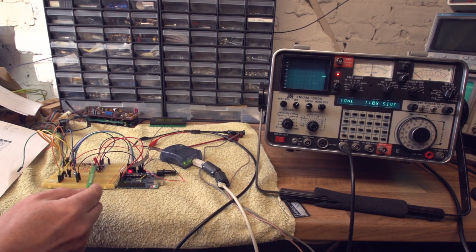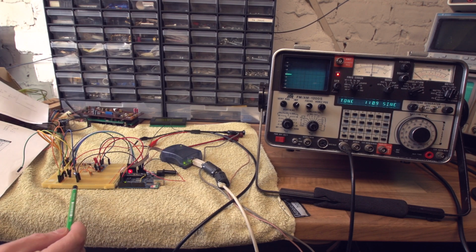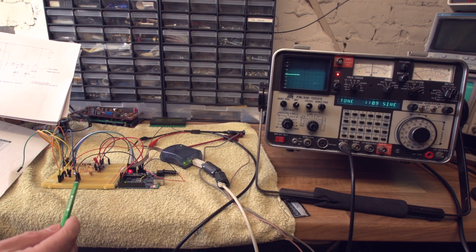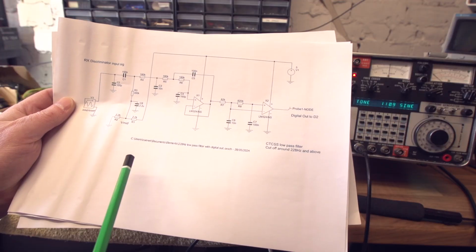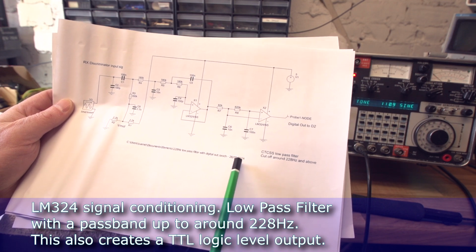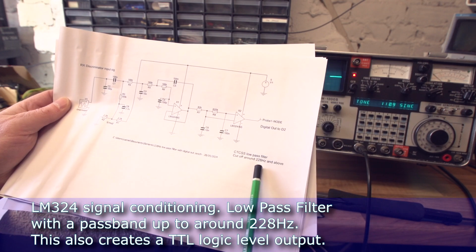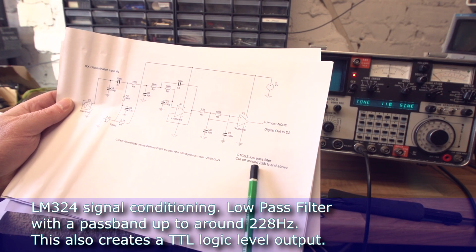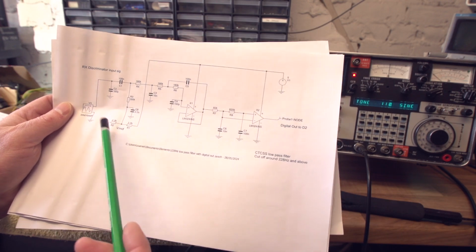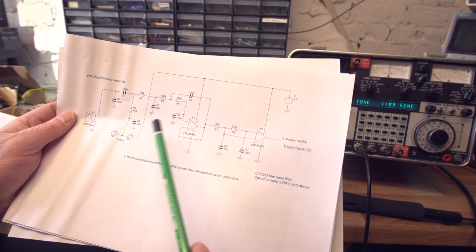Right, there's also a little bit more analog circuitry here. We've got some op amps here. It's LM324, and it's configured in such a way to give us a low pass filter which cuts off at around 288 Hertz. Anything lower than that goes through, and it rejects anything above that. So anything, let's say 300 Hertz and up within the normal audio range, is rejected. So it's only allowing through the CTCSS tones in the sub-audio region.